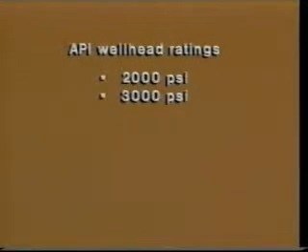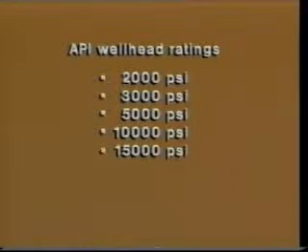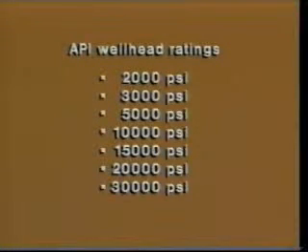Standard API wellhead designs are rated for 2, 3, 5, 10, 15, 20, and 30,000 psi working pressures. Factors such as the presence of corrosive fluids and extreme climatic conditions must also be considered.